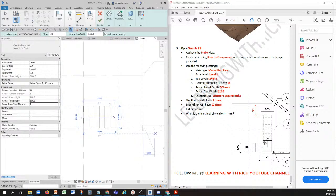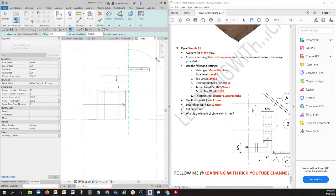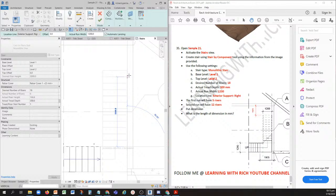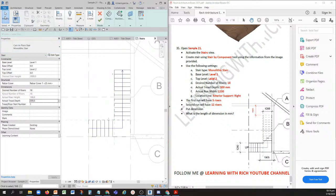And then we're going to create the remaining 12 risers above. So we're going to pick at the intersection here of our reference plane. Oops. Okay, again I picked the wrong side, so I'm going to escape once. So I'm just going to pick here. Alright, and then just use up all the remaining 12 risers. Okay, and then click here. There you go. Then just select modify.